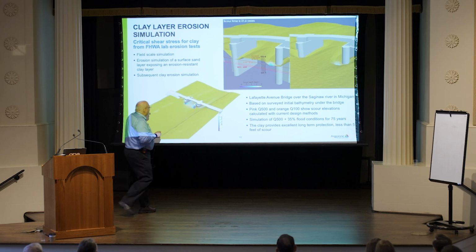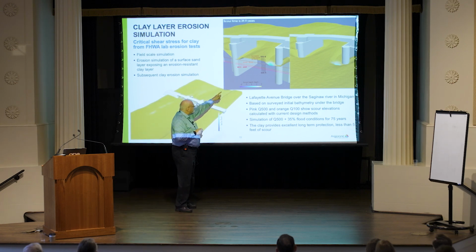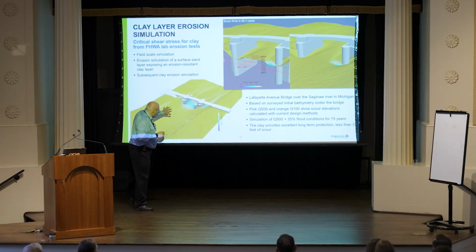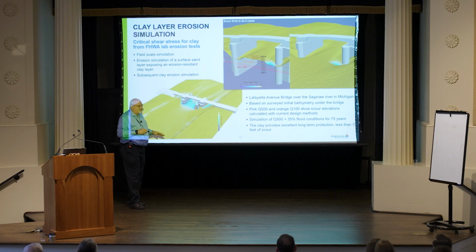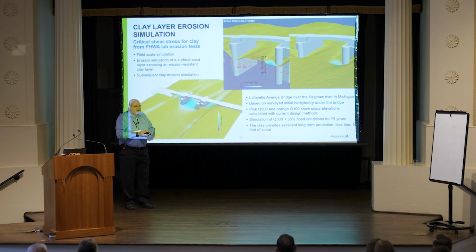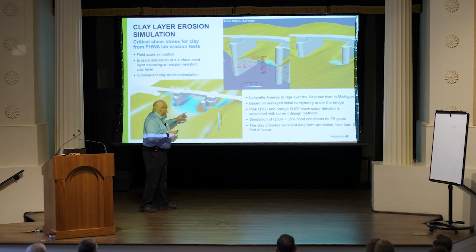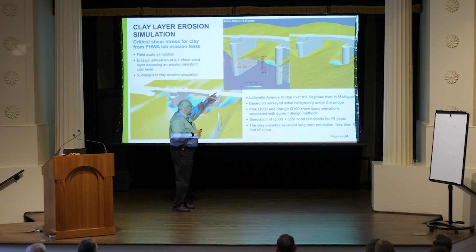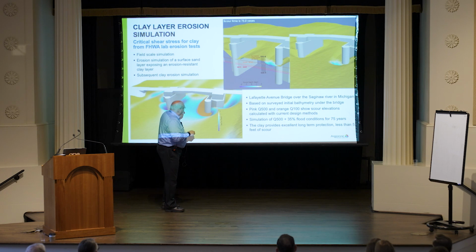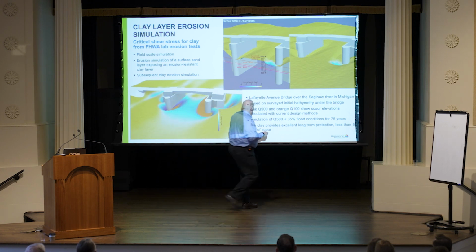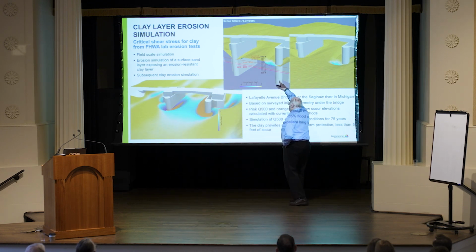So what you see here on the top now is a totally different thing. We start with the final stage that we see here, and then we assume that the riverbed shape with the clay and with the sand is now all clay, right? And that is something that we then can run through a clay erosion simulation, right? And what you easily see is not so much is happening, right? I mean, you have that one dip here by about 4 feet.